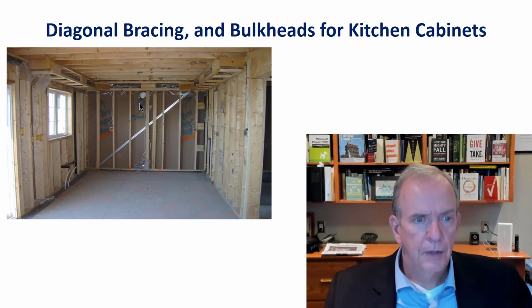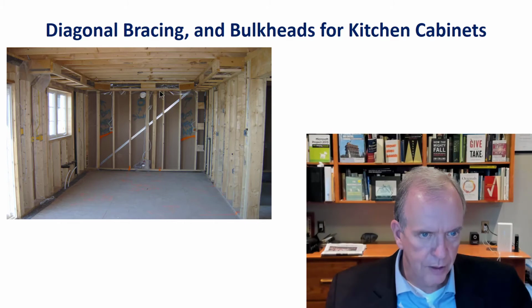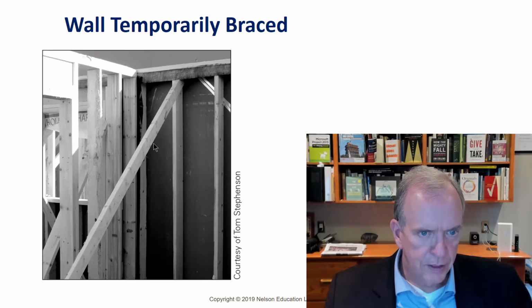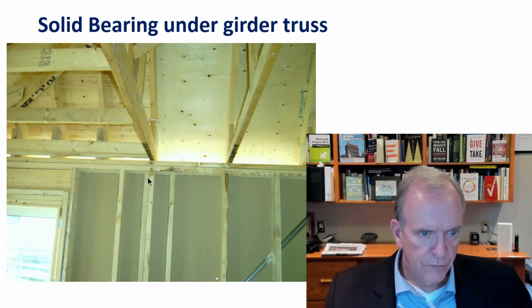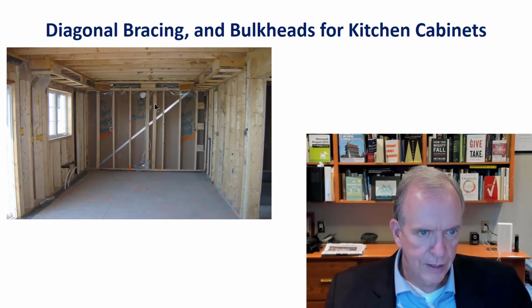So you can see the metal bracing in place here. You see two double studs here. I think when they were doing it, they missed the solid bearing from up above, and they doubled this instead of putting it exactly where it should go. And I think the building inspector made them come back and put double solid bearing here, because I believe in this particular case, this double stud goes right down to the floor below. And that is, if I recall, right here.